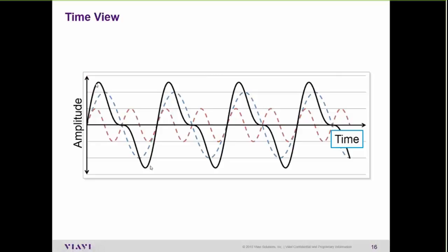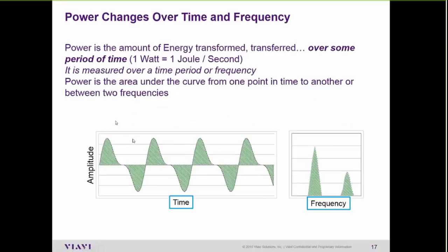And so as those signals add up over time, you're going to see the power vary based on the way the frequencies interact. As they both go up, the signal is going to continue to go up. But once one frequency starts to reduce back down in power, the amplitude of the time varied signal, the compilation of all those frequencies, is going to start to decrease. And you can see here the change in power over time when you sum two different frequencies together. So here we have just these two CW signals, and this is the power over time.